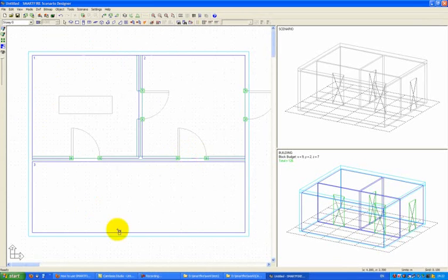In the particular geometry that we have here, the only other additional object that we need to add is the fire, which we will place in the position of the furniture. Remember that this tool is only entering the geometry. There are no settings for the type of physics or the fire output or any other behavior, although we do have limited control over whether a door is initially open or closed.